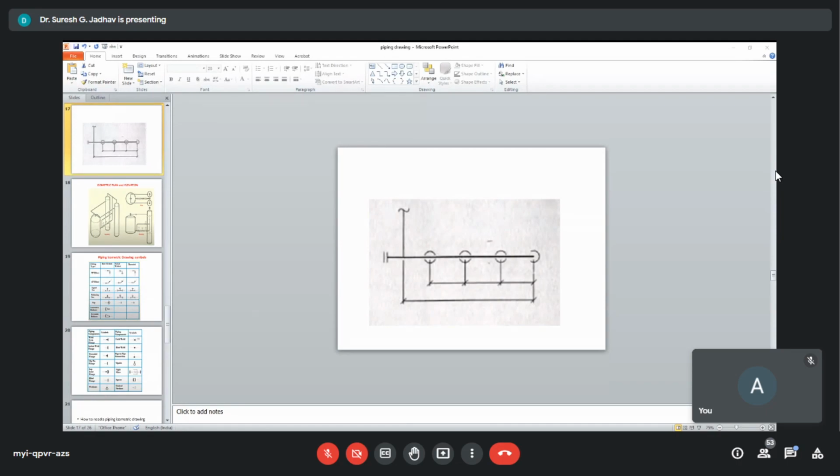For field run piping, give only those dimensions which are necessary to route piping clear of equipment and other obstructions. Locate only those items which are important to the process. Underline out-of-scale dimensions or mark them as NTS, and do not terminate dimensions at screwed or welded joints. Now this is all about dimensioning in piping drawings in different industries.